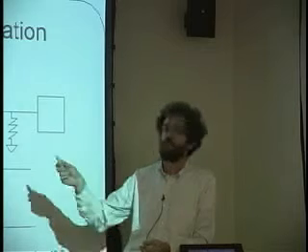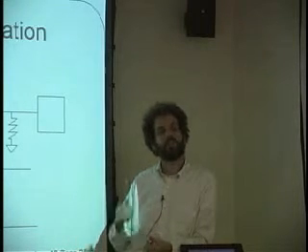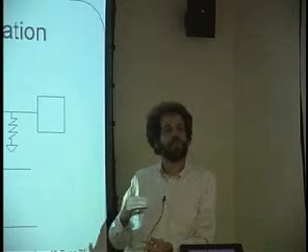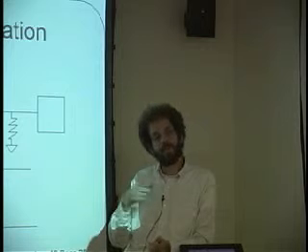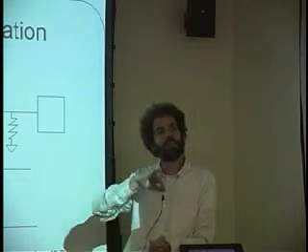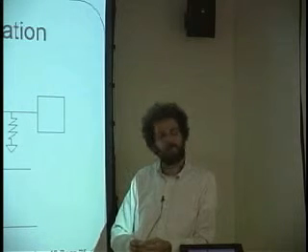If I want to run a computer slowly without terminators, all I need to do is change between 0 and 1 very slowly. The echoes still happen, but they happen in a time that's short compared to the time of the transitions between zeros and ones. So if I don't want to send signals too rapidly in the system, the need for terminators is much less.